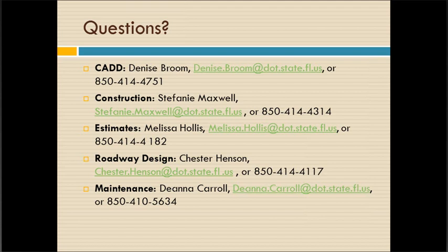Notice that if you're dealing with refurbishment markings, a lot of times the flow chart says you need to talk to the district maintenance engineer to find out how long the service life of that pavement is and how long those markings need to last. The district maintenance engineers will make those calls as to whether they want to put down spray thermo or refurbishment thermo, or whether they want to use durable paint.